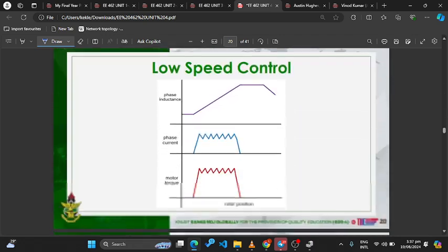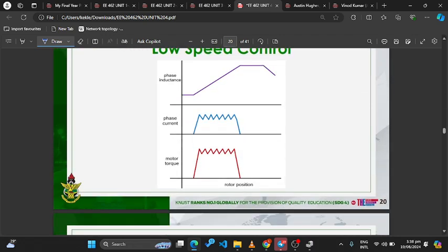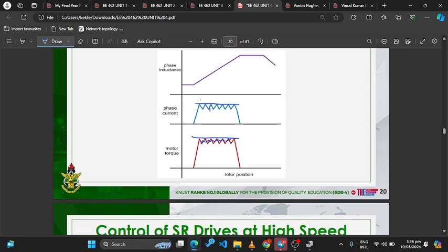Is that okay? So you have something like this. So it means the current can't go beyond this. If it gets here, the current is chopped. If the current is chopped, then the torque is also going to be chopped, because the current affects the torque. Okay, and this happens during what? It's only during the rising phase that we have current flow. We have the current pulse. So what will happen during this phase? That side, the current is zero.